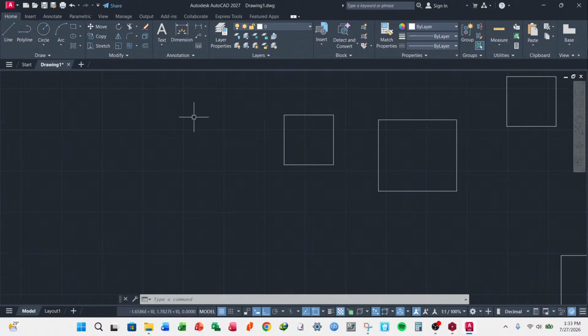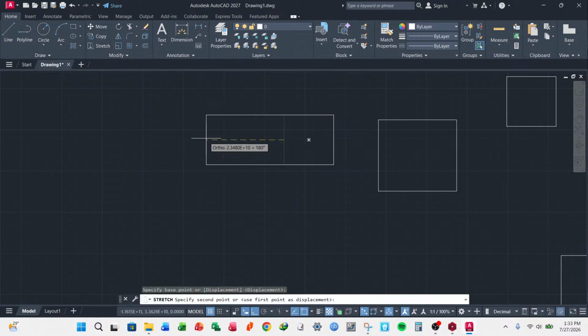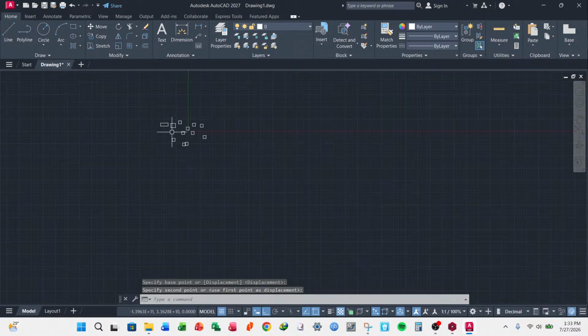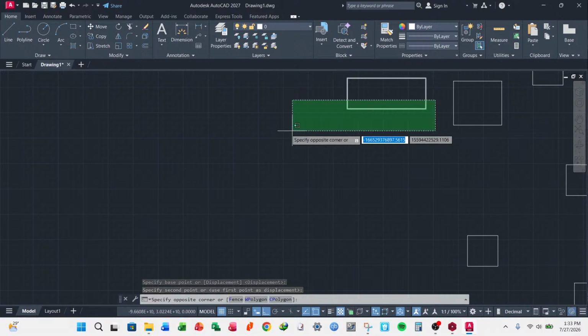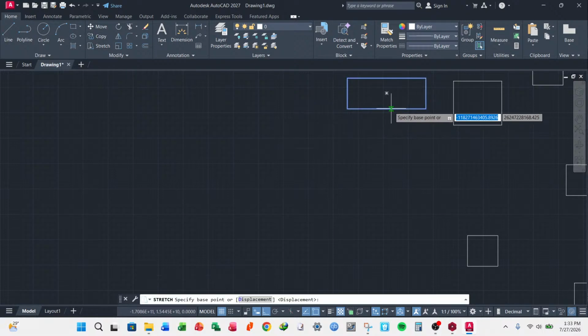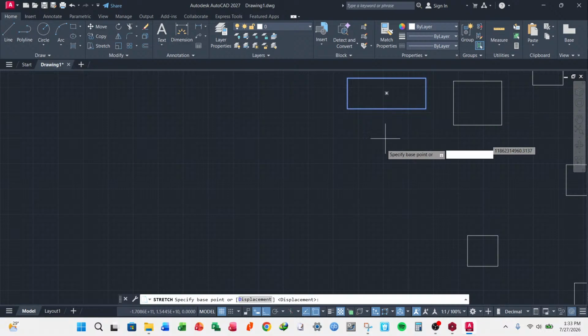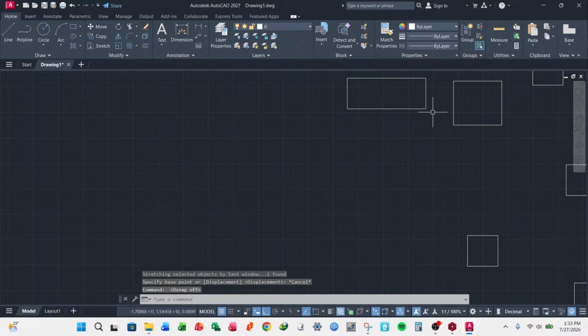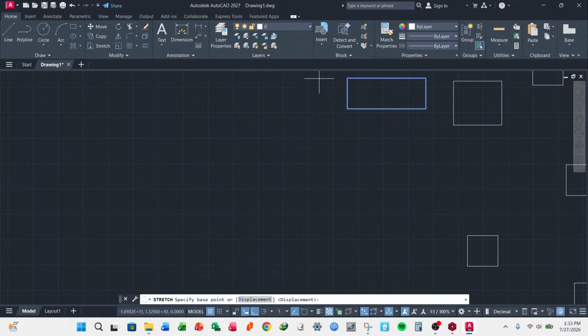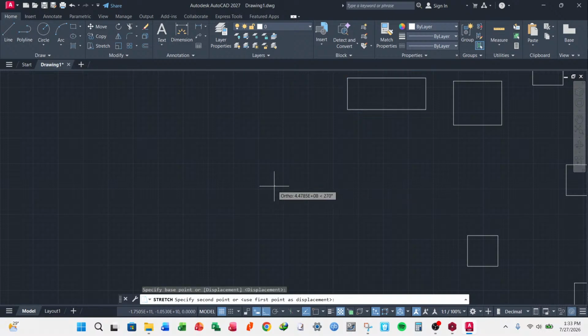As I said, if you want to stretch, use the green box to highlight, then activate your stretch command, tap and pull like that. Now you can do the same vertically. You don't even need to click or snap at the exact object. You can turn off snap, just highlight, stretch, and you can even stretch from here like that.